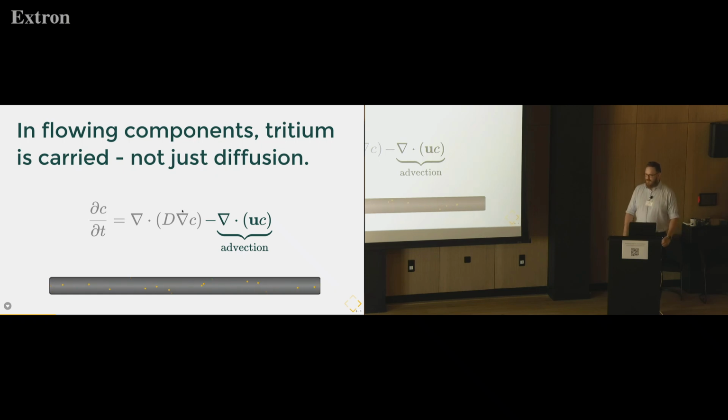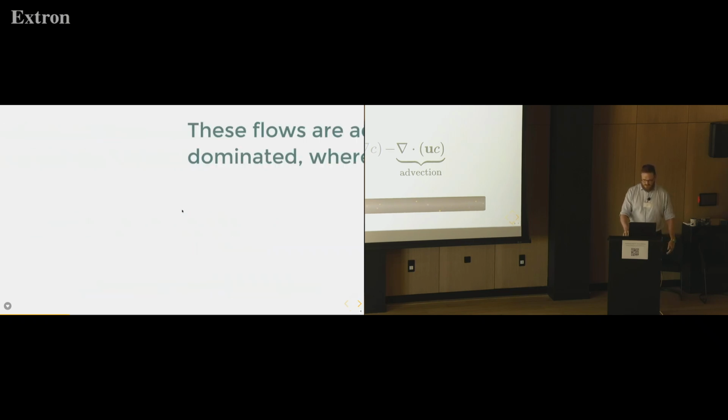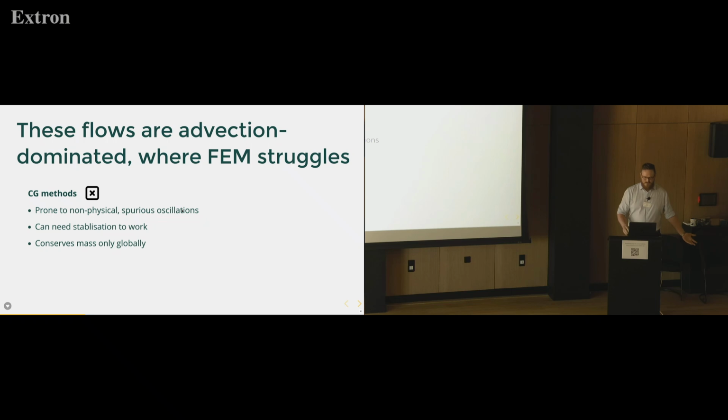We thought in theory you just add this little advection term and then you're off to the races, it's all good. In the title I originally had "this is where FEM struggles", but actually it's just where non-FEM experts, comme moi, struggle. So this was an effort to design a proper DG method for this, because a lot of what we do in FESTIM is just bog standard CG1 methods, and this is where it's very difficult to do any kind of advection-diffusion.